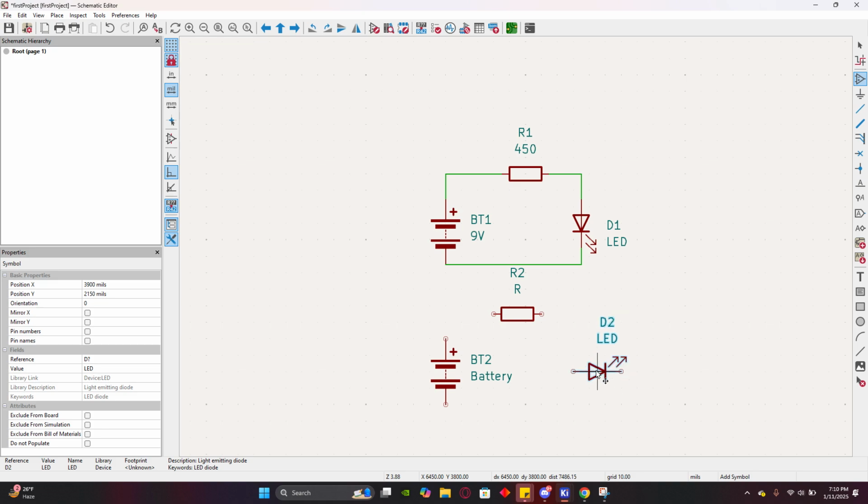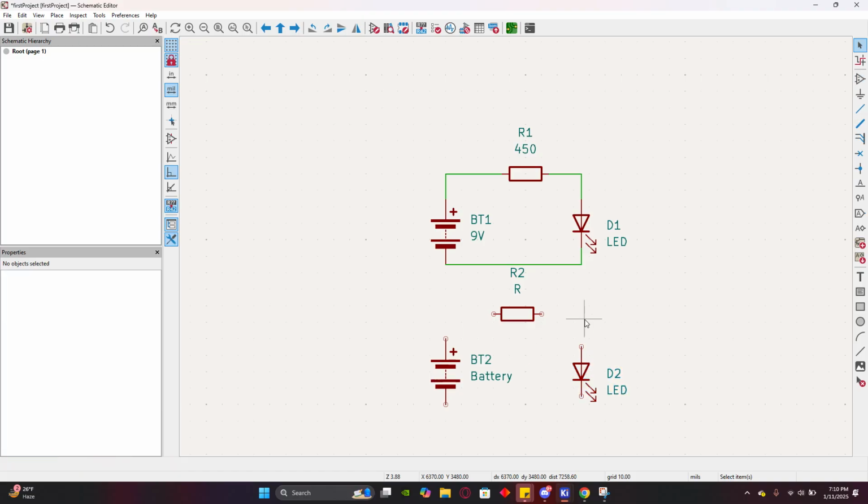All of these are general components, and none of them should have footprints specified. Things like chips usually have footprints, and if you get something online, you want to look for something that has both a schematic symbol and a footprint. You can make both from scratch if you really want, but it's a pain and you don't want to do that.